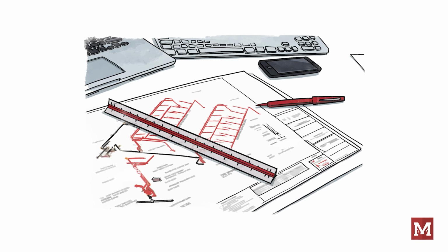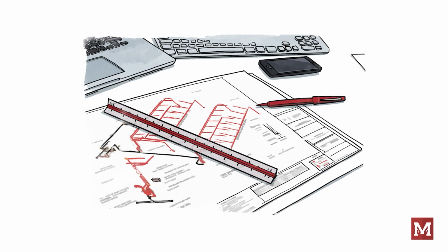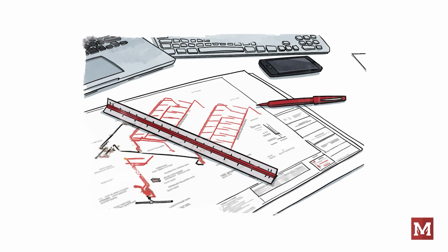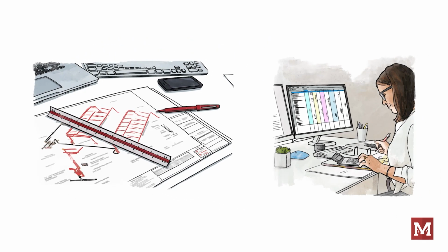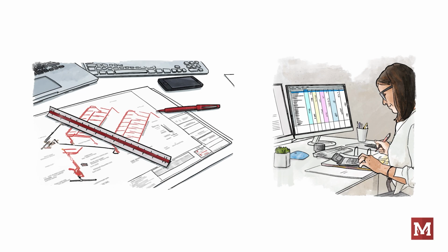This is really important because if my design staff is unable to navigate a set of building plans and glean information pertinent to their job, I may be reviewing automatic sprinkler plans where the branch lines are running in a direction with nothing to hang from or areas of the building that are inadequately protected. If our sales personnel aren't able to read building plans, they may not know that the project will need a dry system or protection in combustible concealed spaces. These sorts of mistakes can have severe financial consequences.